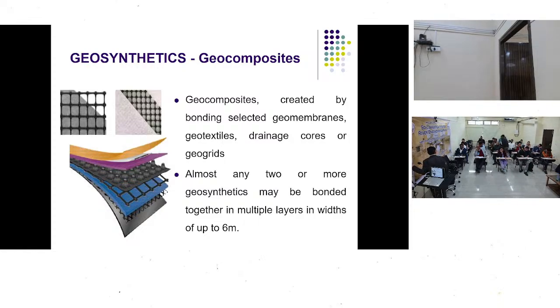Also, it was felt that maybe the flows of water may be high. So they also installed a geonet. And then to monitor whether there are certain leakages or not, they had installed some optical fiber cables between the geonet and the non-woven geotextile. With those optical fiber cables, they had put some temperature sensors. So wherever there was any lowering of temperature, this means there is certain leakage.